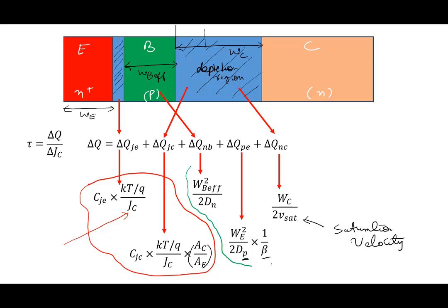These are all, to first order, independent of collector current density. They go by the name transit times. We just call them transit times. So two blocks of delay that you see: one component dependent on current density, the other component first order independent of current density. All right, so what we want to do is